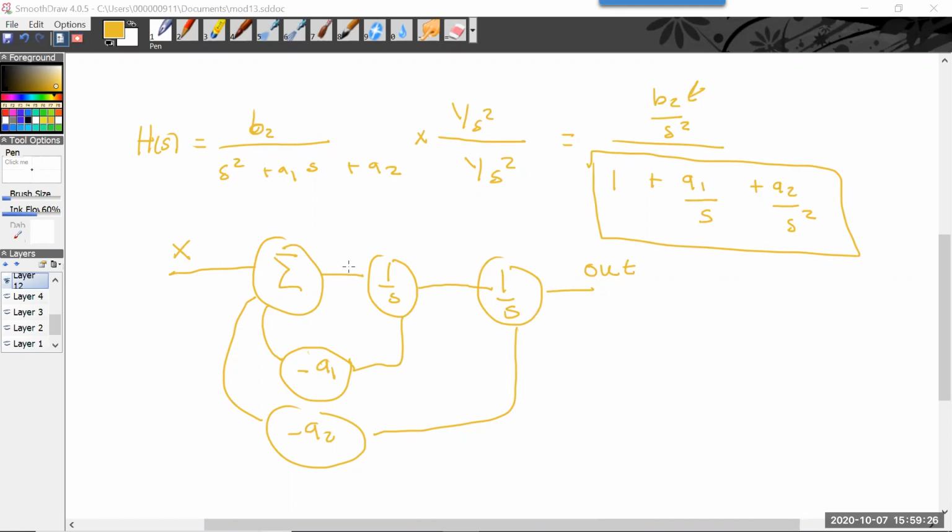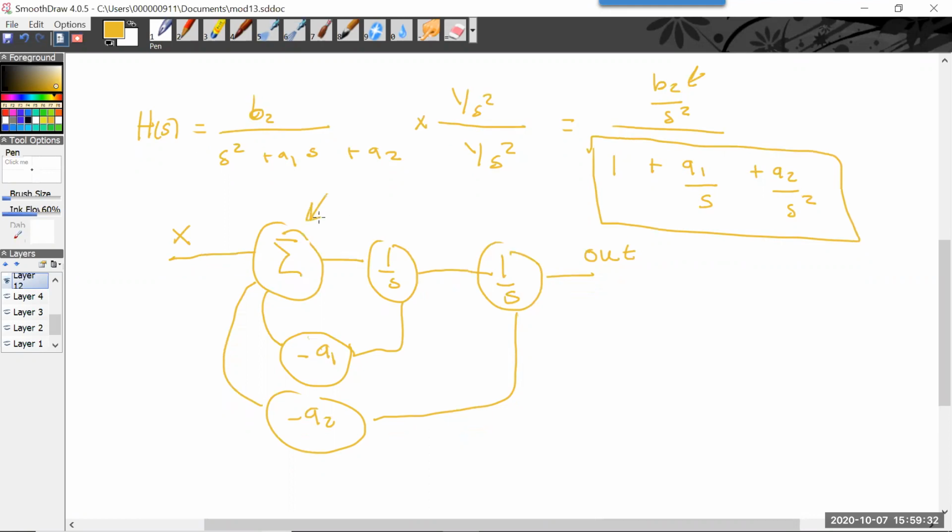So now the next part is converting this into a circuit. All right. Now summers, you know, and actually integrators, you know, right? So summers look like this, and integrators look like this, except it's 1 over RCS, right?